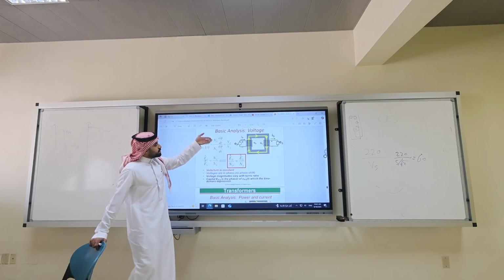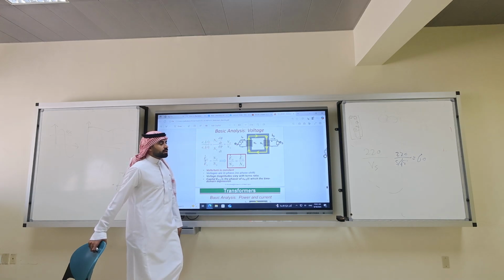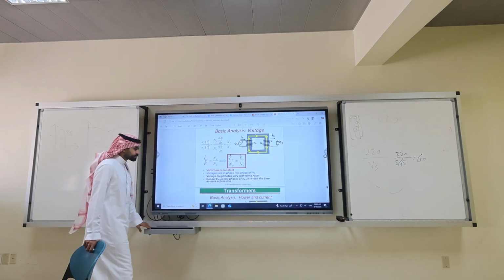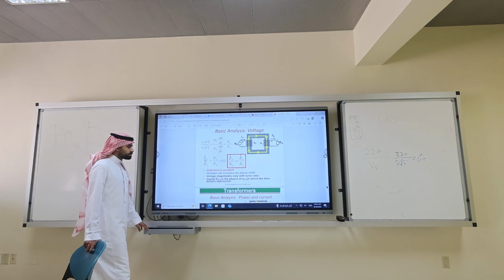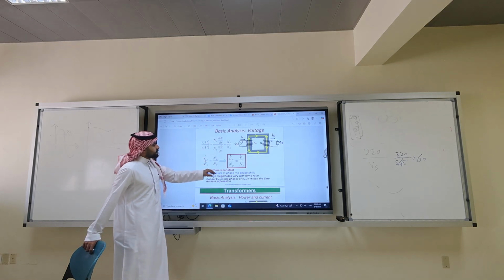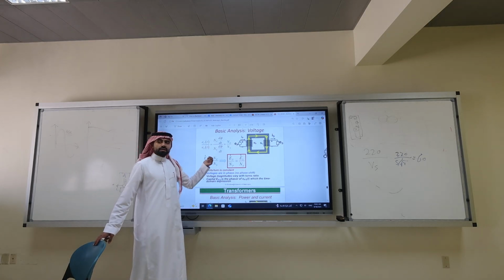Then you make division. So N primary over N secondary. Cancel the rate of change of flux. You will have this formula. I will fix it. The PDF was corrupted. I don't know why the PDF corrupts the phasors. I need to use another technique. But anyway, this is phasor EP equal NP over NS. I use this formula. Some students won't use this formula, but I prefer this formula.